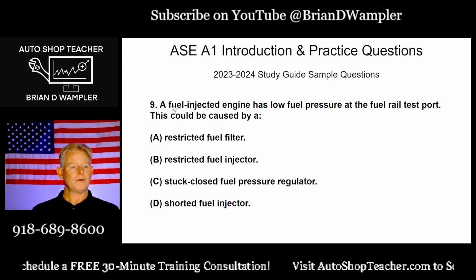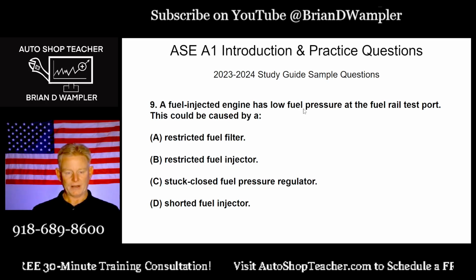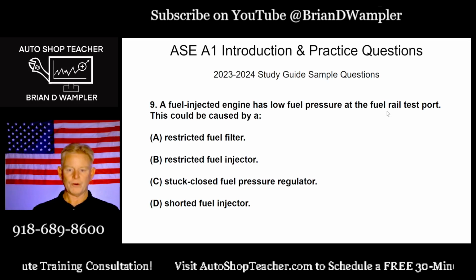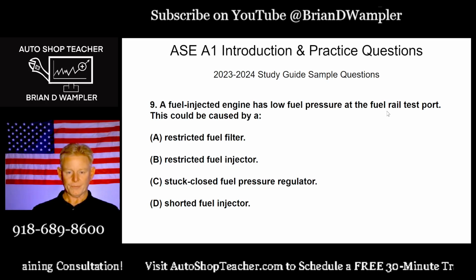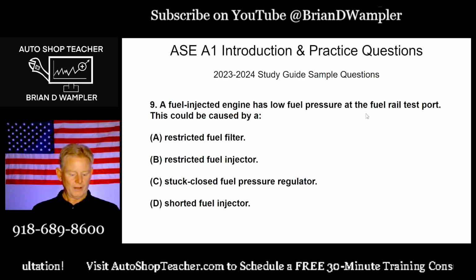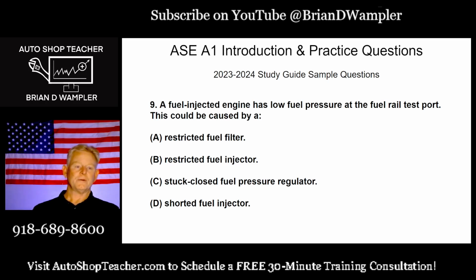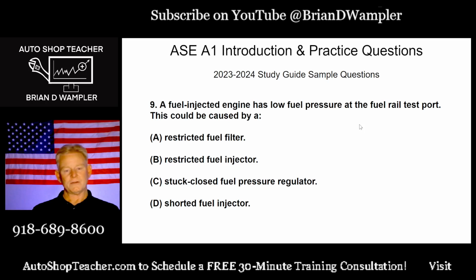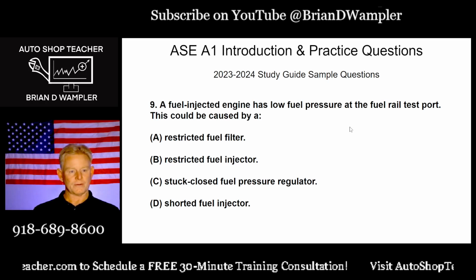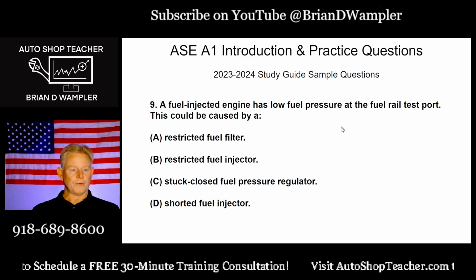All right, so we know that we have a fuel injected engine that we're doing a fuel pressure test. It has a low reading, and we know where we're connected. We're connected to the test port located on the fuel rail. So it's some sort of fuel injection type system that uses a rail type. So either a common rail GDI or maybe it's port fuel, doesn't really matter. And since we're not told, we don't need to add that into our factoring for the answer on this. So we're talking about low fuel pressure at the test port.